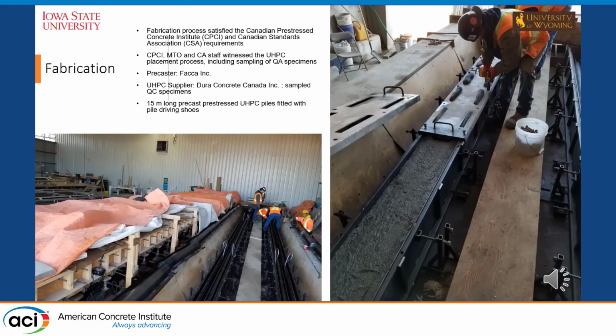As for fabrication, we are a CPCI certified plant. We have a 15 meter pre-stressing base, so that's why we cast our piles to 15 meters to accommodate the 13 meter design. MTO, CPCI, and all the engineers are there to witness the casting. So here are just some pictures of it.